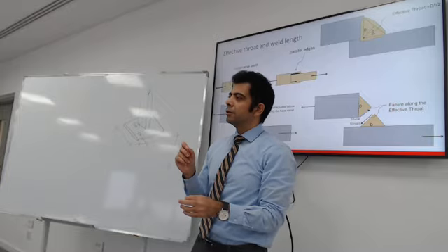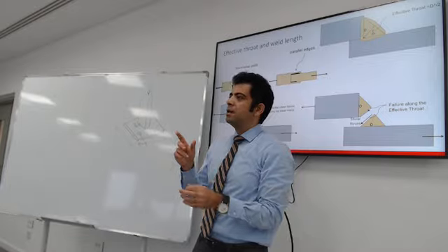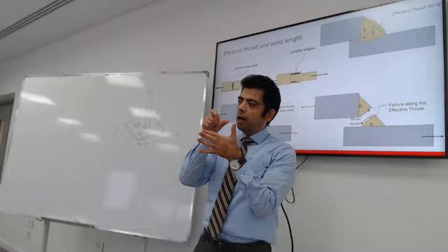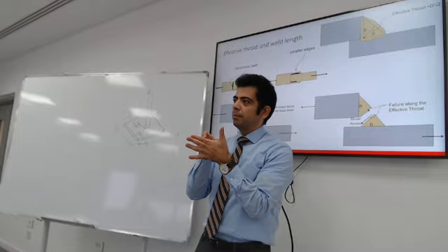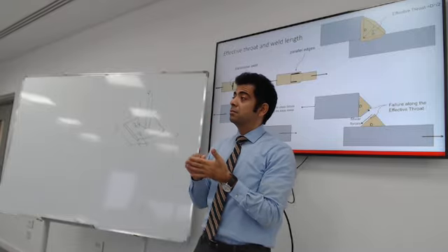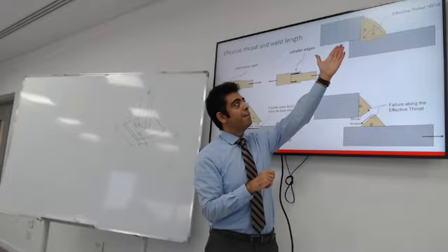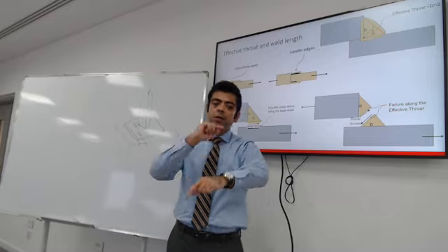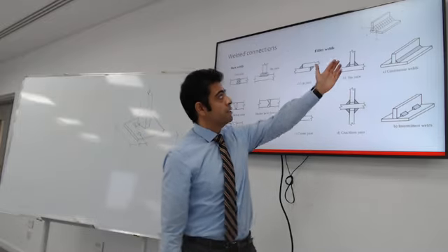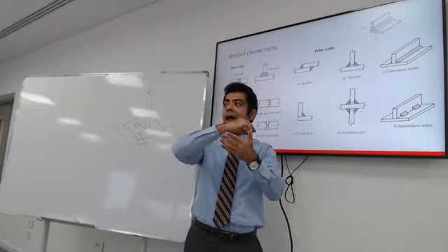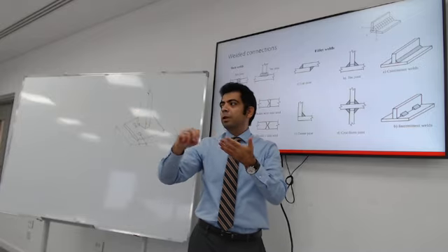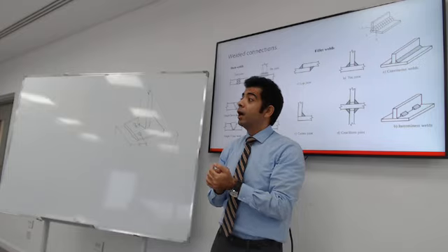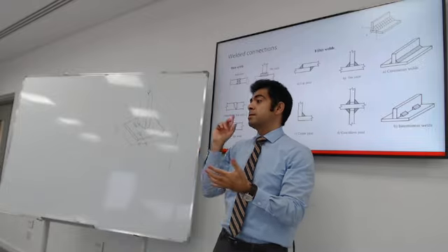These are interesting thoughts, but in any case, you cannot spend too much time or too much power on a certain spot at a time. You need to apply it in layers. So if you require a big size weld, you cannot do it in one pass. You just need to do it over layers. That's what I mean. There is layer 1, and then you add layer 2 onto it, and then layer 3, rather than just spending a big amount of pool of weld on a certain spot. It will cause problems I will talk about in a bit.